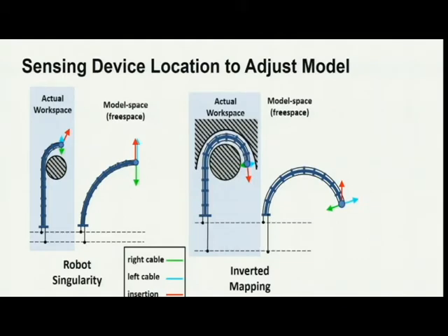Another classic, canonical example, so again, same tendon displacements, no contact. Again, there's this insertion axis, which is the red. In this configuration, when you insert in the red, the whole device moves up. But if you're stuck in a channel like this and you're banking off the top of the channel, when you insert the device and push up, the tip actually comes down.